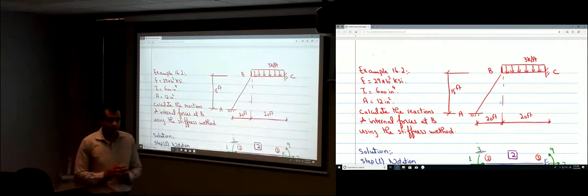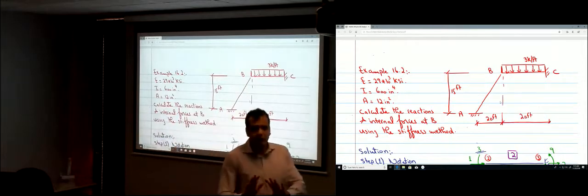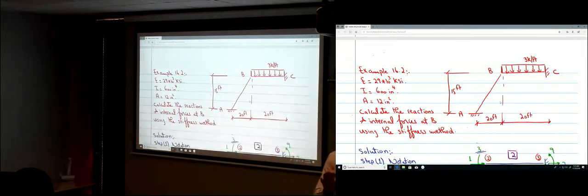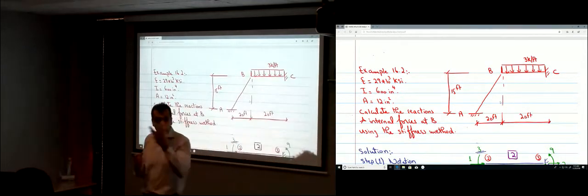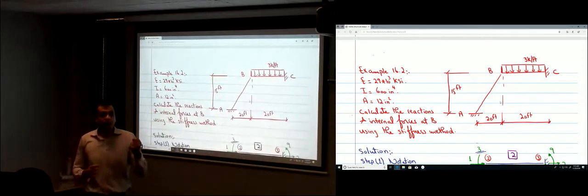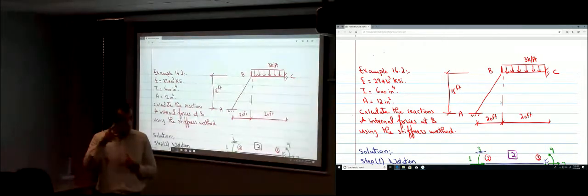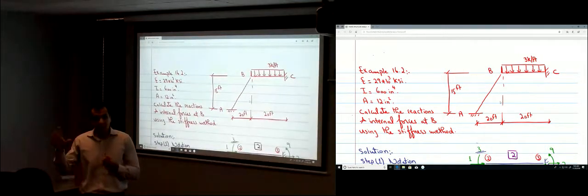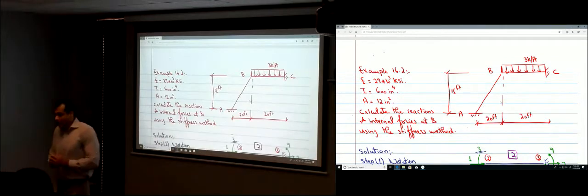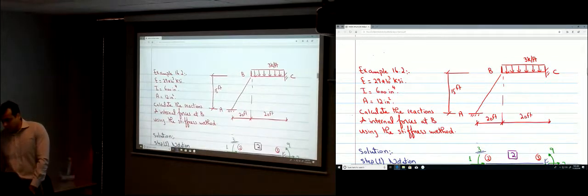Not yet. Are you talking about using cosine and sine? No. We're using P, the internal forces. The internal forces are forces, right? P equals KU. That's the only thing that we know here, the stiffness equation. What P are you looking for? You're looking for local forces. So you're using P local equals K local times U local. Everything is in the local direction to find the local forces, in the direction of the member itself. So how does this look? We wrote this before here.